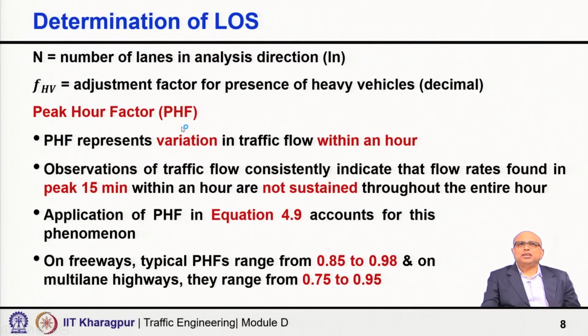So, the peak hour factor, as I said earlier, represents variation in traffic flow within an hour, and observations of traffic flow consistently indicate that flow rates found in the peak 15 minutes within an hour are generally not sustained throughout the entire hour.